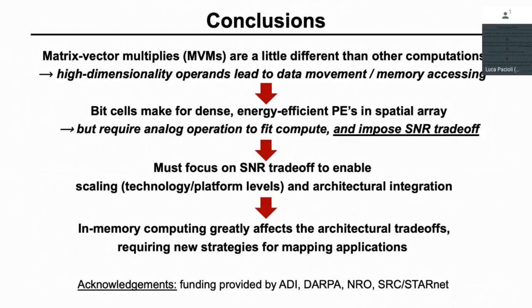Question here. When you were describing this SNR trade-off and in terms of using multiple bit lines, I wonder when you do the comparison on energy efficiency, a fair comparison would be actually in the conventional implementation, maybe the supply voltage could be lowered and essentially they achieve also lower SNR, but it comes at the benefit of energy efficiency.